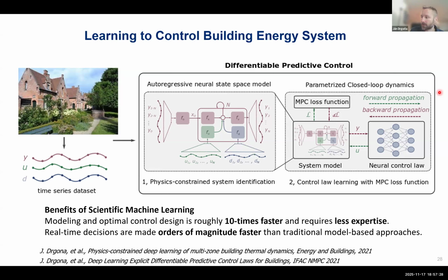The problem with MPC for buildings is not that we don't know the physics. We know the physics, but obtaining these models is very, very expensive. Getting a high fidelity digital twin in Modelica can take months of time. And then formulating MPC problems with these high fidelity models is computationally expensive and potentially leads to numerical issues, because we are dealing with differential algebraic equations. You can have algebraic loops, and you can have stiff system dynamics because you have slow dynamics and fast dynamics of heat transfer in buildings and HVACs. So things get complicated very, very fast when you want to do everything model-based.